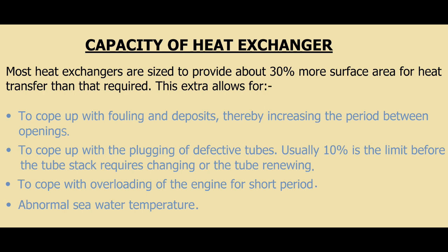To cope with the plugging of defective tubes, usually 10% is the limit before the tube stack requires changing or the tubes renewing. To cope with overloading of the engine for a short period. To cope with abnormal seawater temperature.